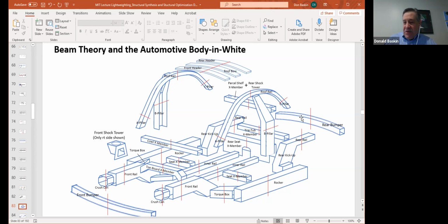And in a rear impact, you can also see how the load is similarly distributed as it would be in the front, except it feeds in from the back of the car and then distributes itself to the rocker panel, the rocker rail, and then in some cases, depending on how well the car's engineered, also to the rear rails. I'm sorry, the center rails. These guys here, the inner rails.